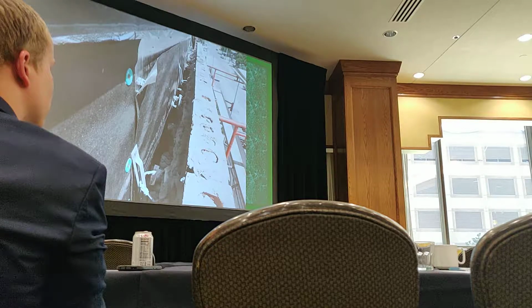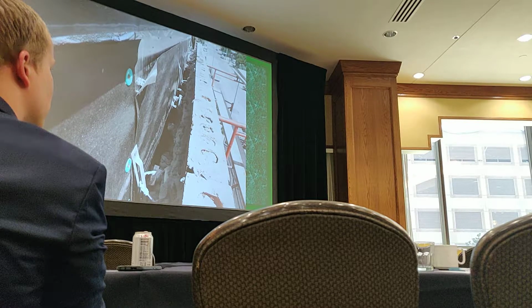So these need to be, by the prescriptive requirements, at least an 8-penny nail, and at top and bottom, so you can actually adjust the tie. So this brick was rotating outward over the sidewalk.